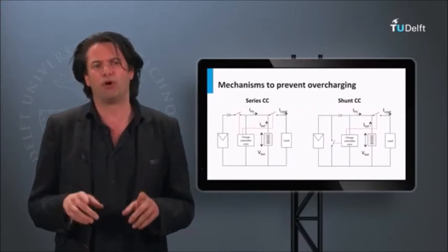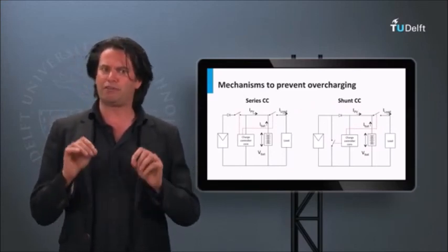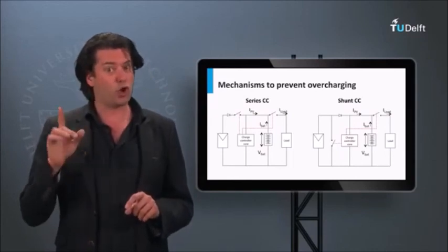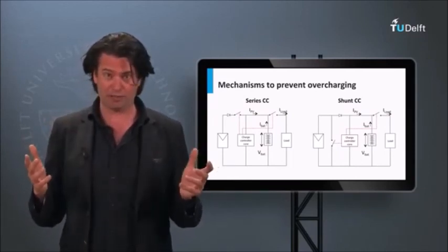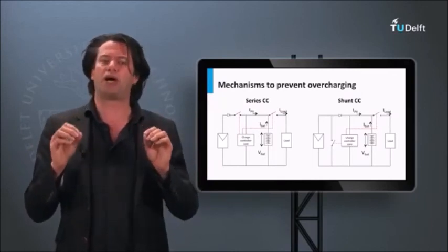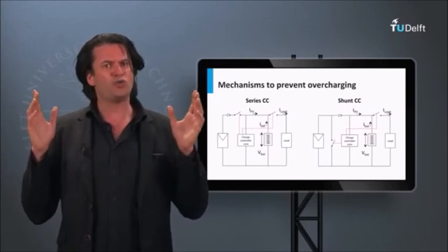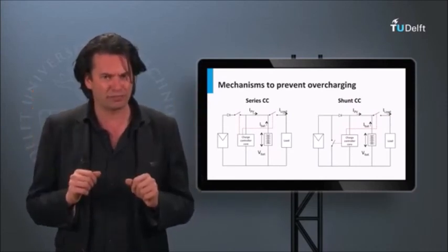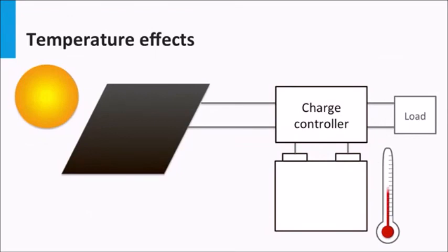We have seen in the previous block how the temperature plays a crucial role in the functioning of the battery. Not only does temperature affect the lifespan of the battery, but it also changes its electrical parameters significantly. How does the charge controller handle this situation? A good charge controller these days comes with an inbuilt temperature sensor. Therefore, it compensates for temperature fluctuations and dynamically decides how the electrical specifications like operating voltage change with temperature. It successfully keeps the battery operating in the desired range of voltages depending on the temperature.